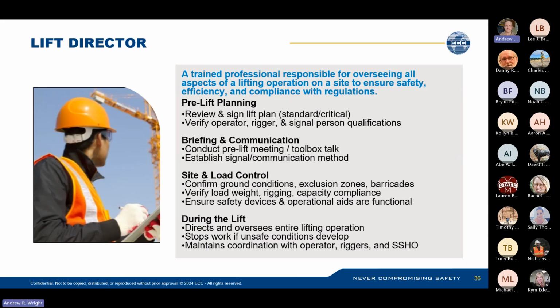They're going to conduct pre-lift meetings, toolbox talk meetings when the crane is on site and being used, establish a signal communication method, site and load control. They're going to confirm ground conditions, the exclusion zones, the barricades, verify the load weight, the rigging, and the capacity compliance, ensure devices and operational aids are functional.